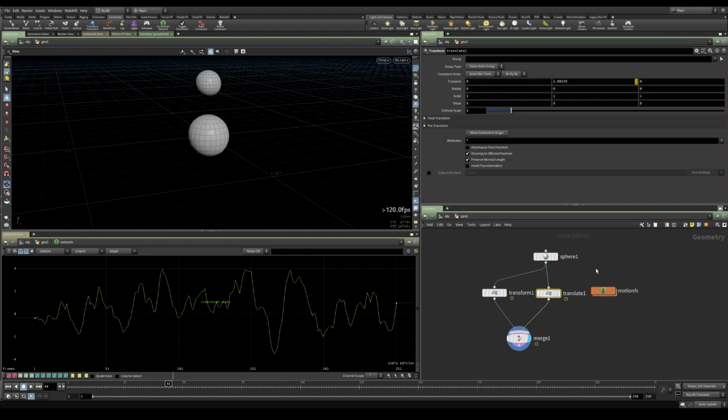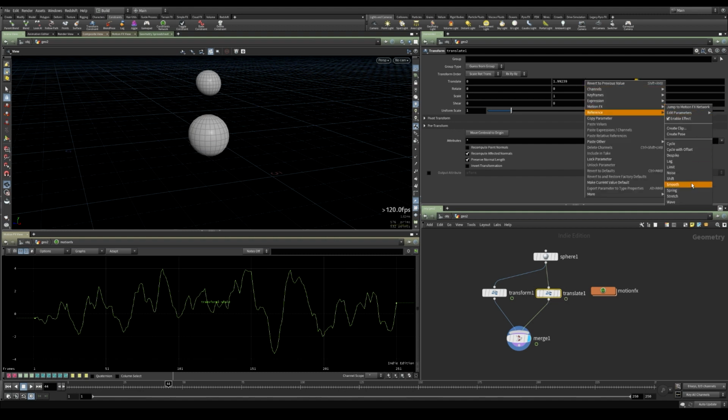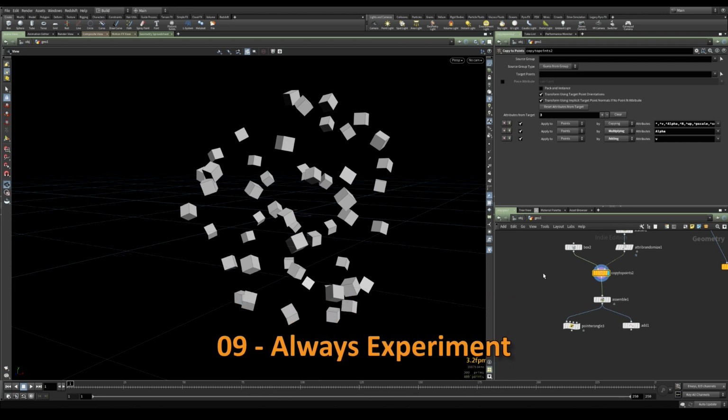And that's basically it. I honestly don't use chops very often, but this MotionFX preset stuff is pretty convenient if you want to do some quick animation. And for this tip I chose the wave and the noise operator on purpose because they actually create animation. If you want to experiment with the other ones, keep in mind that the smooth, the shift, the lag and other ones are intended to modify a previously existent animation. So if you want to see how they work, you need to do some animation prior to the chop network operation itself.